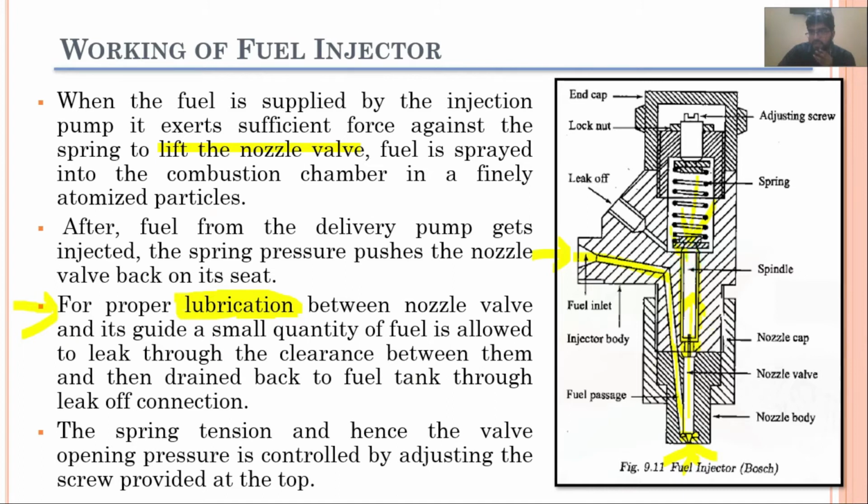When it gets into this spring component section, this fuel would then leak off, pass through this leak off passage into the section where it can be reused or pressurized again. So this is also a very important point. The lubrication between these moving components is done by the fuel itself.